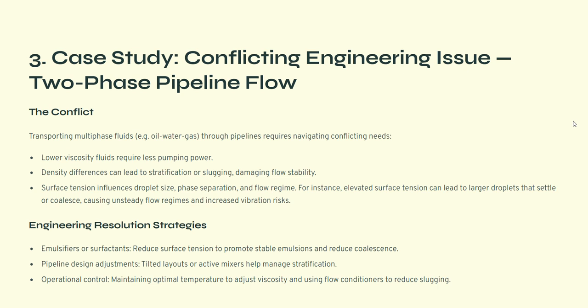Now, for the case study, a common challenge occurs when transporting mixtures like oil, water, and gas. Lower viscosity fluids reduce pumping costs, but density differences can cause stratification or slugging. Surface tension can cause droplets to coalesce, leading to unsteady flow.